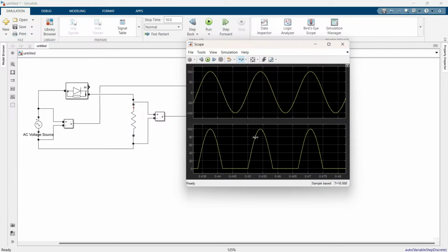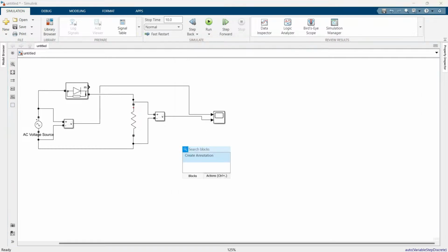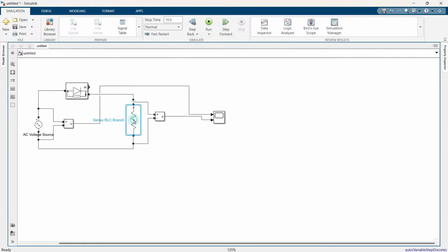So what is the output here? This is the pulsating positive half cycle. It shows the pulsating positive half cycle of the input. Here the output of the half wave rectifier has too many ripples and it is not very practical to use the output as a DC source. So we are going to smooth this pulsating output by using a capacitor.